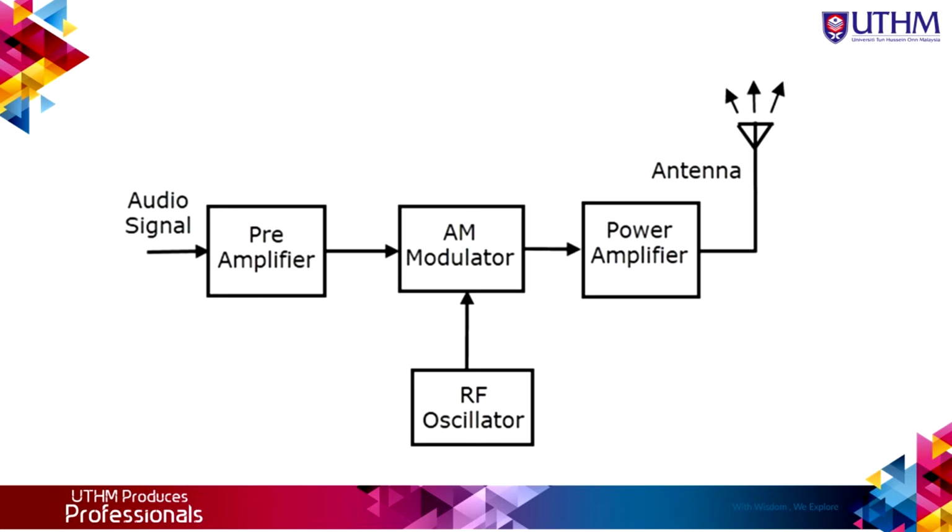Next will be the AM receiver's explanation. It should be cost effective. It should receive the corresponding modulated waves. The receiver should be able to tune and amplify the desired station. It should have an ability to reject the unwanted stations. Demodulation has to be done to all the station signals, irrespective of the carrier signal frequency.